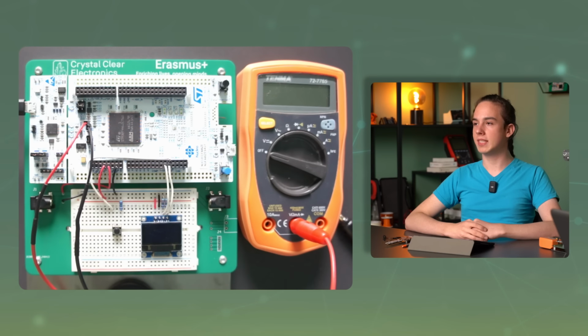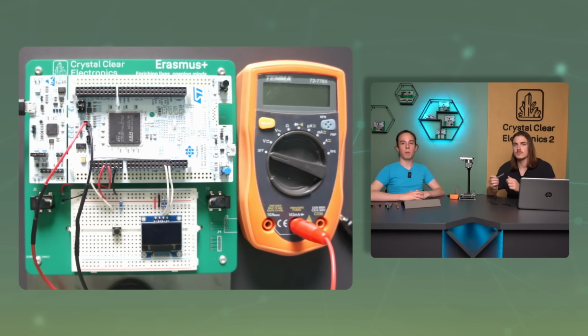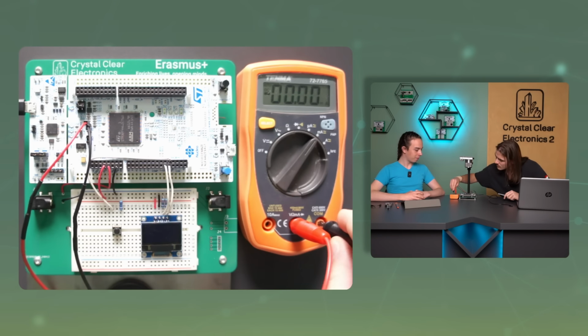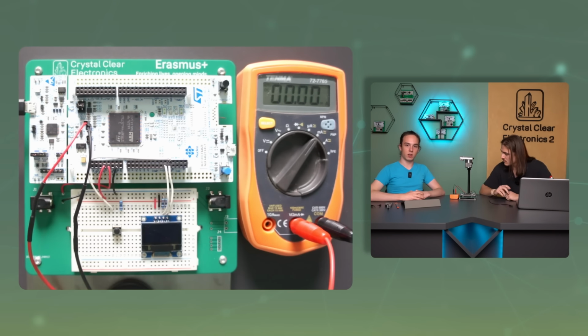The microcontroller on the panel is powered via the jumper marked JP5. You can easily measure the current of the microcontroller by disconnecting the jumper and connecting the multimeter in current measurement mode. For this, we use this wire, one end of which fits on the pin header connector and the other end has a banana plug. On the panel, the microcontroller operates from a 3.3 volts supply voltage, but you can also measure the exact voltage of the 3.3 volts power trace to check the value.